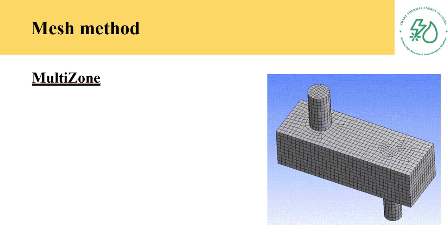When the multi-zone mesh method is selected, all regions are meshed with a pure hexahedral mesh if possible. It uses hexahedral mesh as much as possible. To handle cases in which a pure hex mesh won't be possible, you can adjust your settings so that a sweep mesh will be generated in structured regions and a free mesh will be generated in unstructured regions.